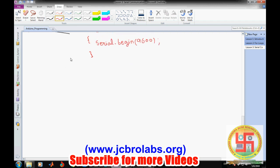Now in order to transmit the data over the communication channel, we have two commands. That is Serial.print, it is in small letters, and whatever text string you want to transfer. It should be remembered that whatever we transmit over the channel is considered a string. Whether you are transmitting a number, a string, a character or a hexadecimal number, everything will be a string. And I hope you are also familiar with the ASCII codes. Those ASCII codes are actually being transmitted over the channel.